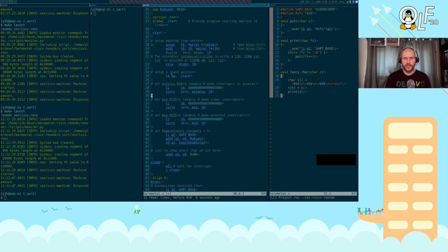For a while, I didn't set up the stack, and when I'd call a C function, it would just keep overwriting the same spot because there's no stack pointer. Basically, there was no stack, and I couldn't return out of the function, so it would just execute off into nowhere. It was kind of mysterious behavior, but that's what it is: you don't get any of those luxuries. You have to set that up yourself.